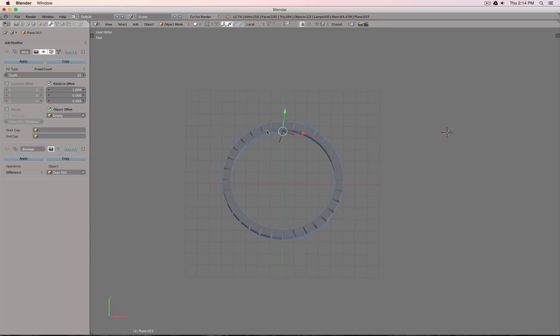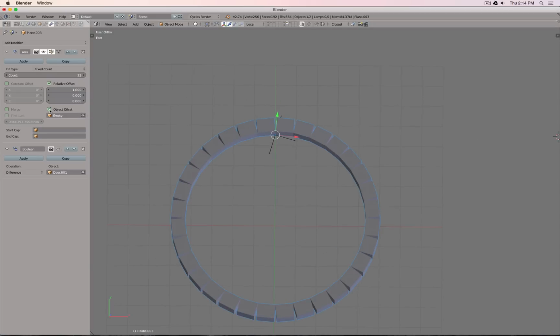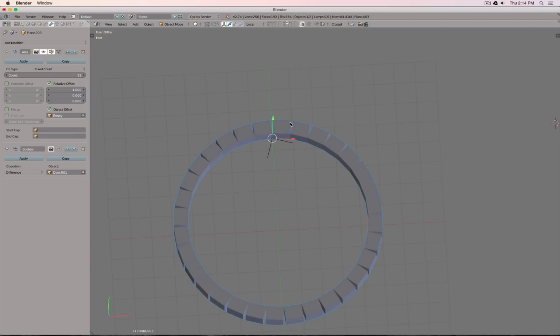Well, we could also do the opposite. We cut those gaps in the inside, but then we have to file a certain amount of material out. So when we fold it, you see here those triangular shapes are open. Think about the reverse. The triangular shapes here are filled because we sand it in small gaps to be closed. The reason why I like this a little bit more is it's less work. I don't have to sand all those gaps perfectly.